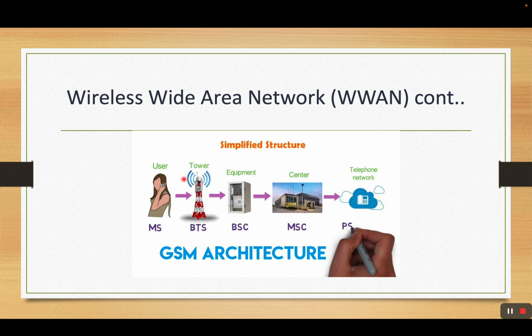The BTS, the tower and the components, what we call the base transceiver station, and the BSC equipment, which is the base station controller, the things we discussed previously. And eventually it's going to be routed to the MSC, the mobile switching center, which verifies the credentials of the subscriber and determines whether the call is local or roaming.